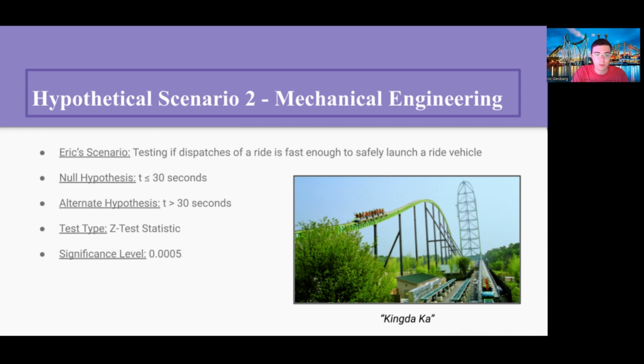One scenario this can be applied to is the launch on a roller coaster. In ride design, to ensure no vehicle crashes into another, there must be a point on the track where the vehicle can be stopped in between each ride vehicle. When there is a launch, it cannot be stopped on the launch, and this is usually followed by a large section of track with no brakes.